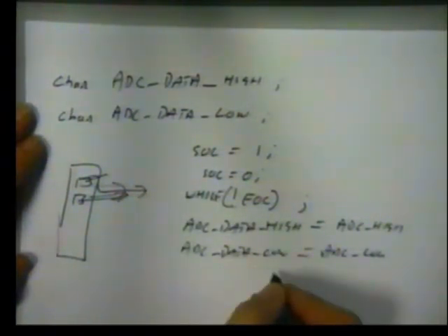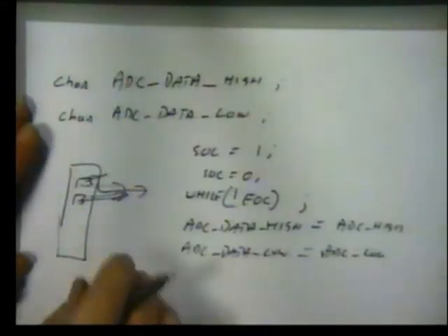We could offset it, scale it. There's no problems with the memory map here, because it is a single process, everything exists as the same entity. So we can declare our data variables, we copy the data over from the ADC memory map into our local memory map and process it. We can just run. That's what you achieve with polling, very simple data structures. You can't do that with interrupts. Why? Because you never know when the blasted things are going to happen.